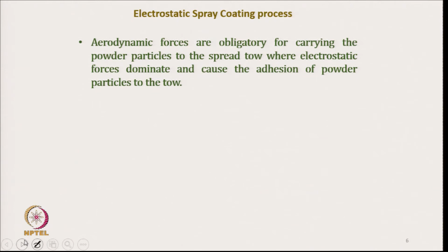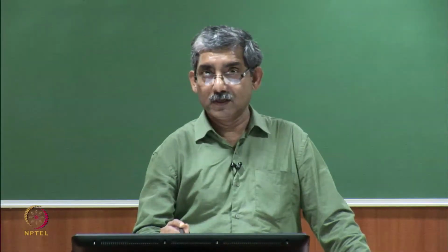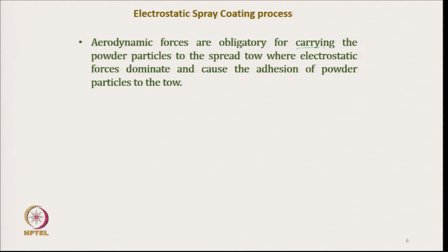So, aerodynamic forces are important to carry the powder particle to the sprayed tow. The carbon tow is not a single filament, it is a multi filament, a large number of filaments are there. So, we need to spray it so that the particles are deposited on almost individual carbon filament.